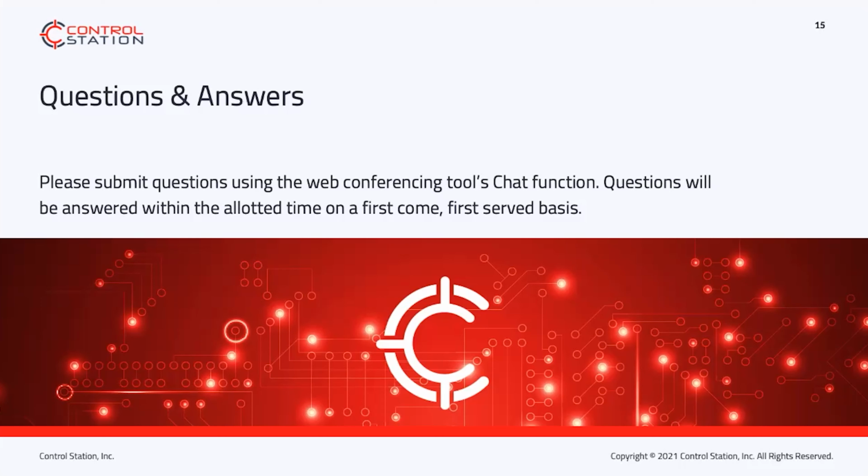Okay. So this next question is definitely one of the big questions for customers and engineers when going out and tuning. You recommended that a step test needs to dominate the noise within the process. Can you be more specific and give people a sense of how big of a test is needed? What we have discussed is that as large as possible is the more politically correct answer, but 3 to 4 times the noise band, at least it should be. Okay, 3 to 4 times the noise band. That's a good rule of thumb.